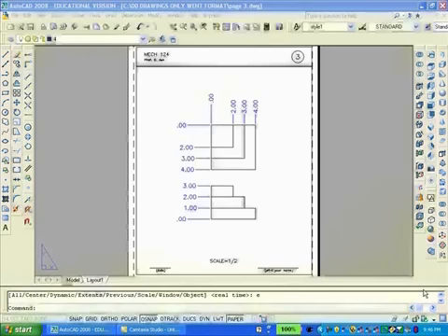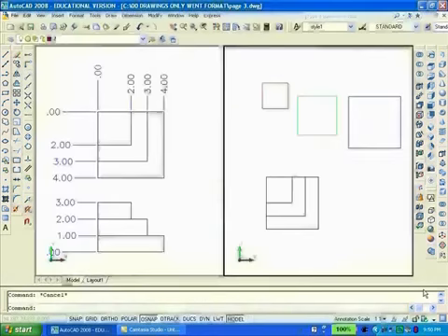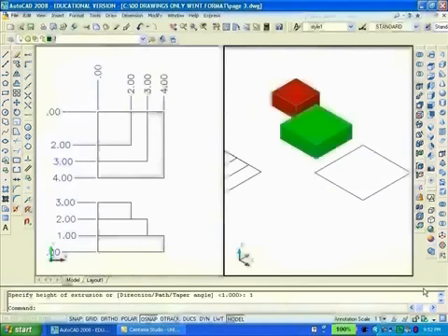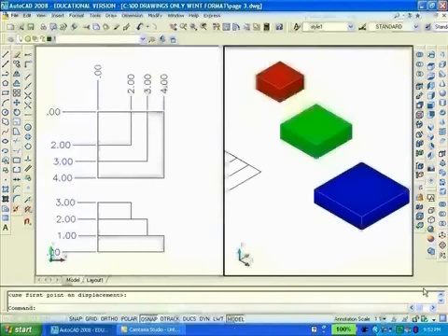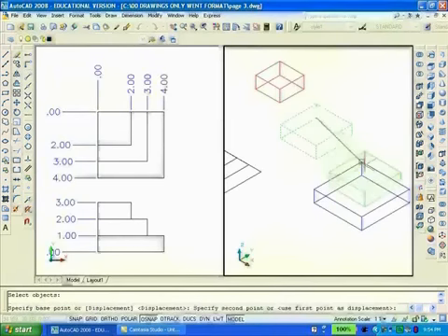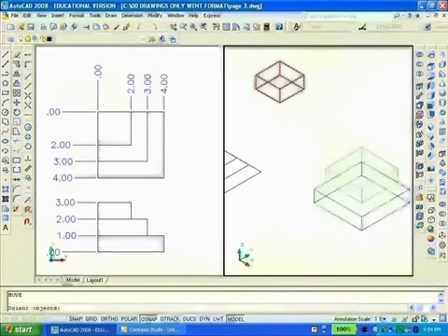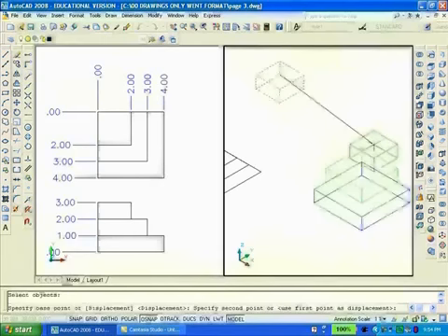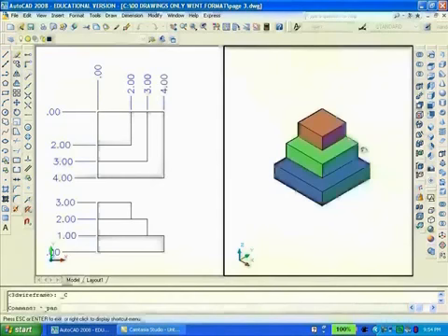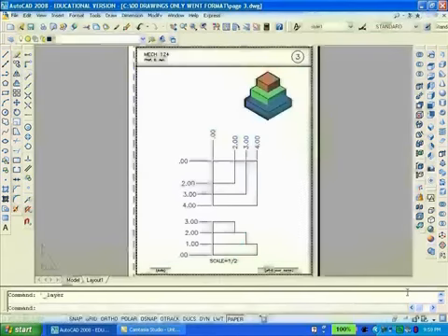This drawing consists of 3 solids which have not been joined together. I use the rectangle command and trace over 3 squares in the top view and move them to the upper right. Go to southeast isometric and extrude all squares to a height of 1 unit. Change the colors of the boxes and move them to the desired location. When that is done, I'll render the objects and the solids will be complete, but they will not be joined. At this point, I can click on the Layout 1 button and move into paper space, create a small rectangular viewport for the new solid.